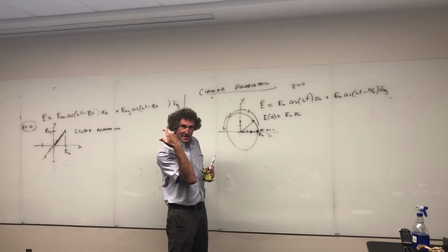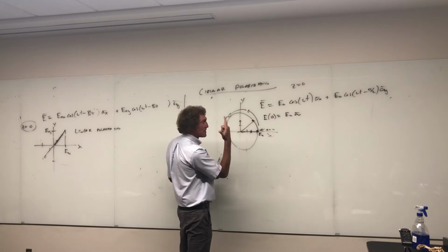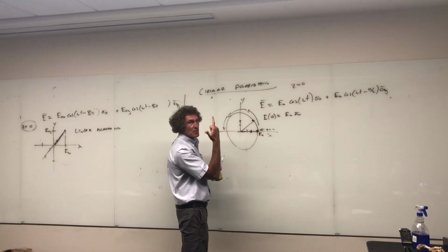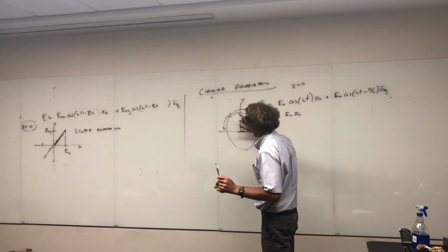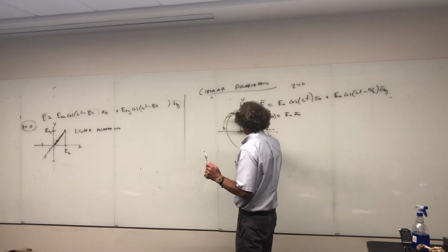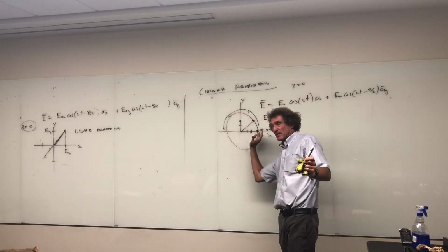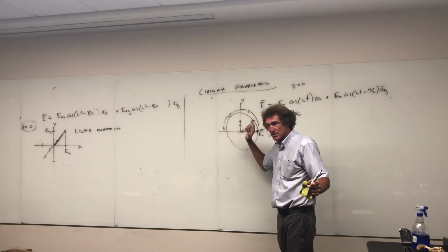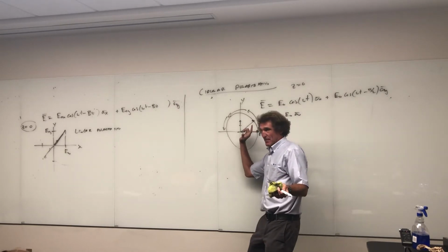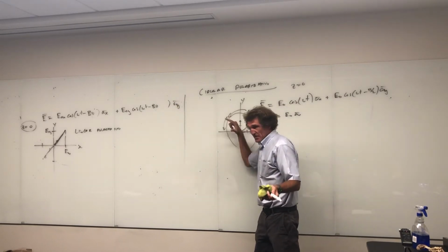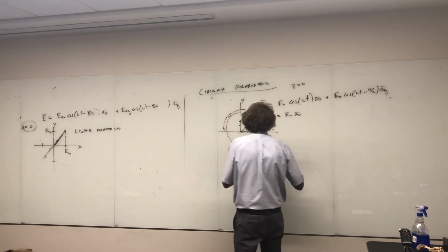If I take my right hand and put my thumb in the direction of propagation, then if I let this thing rotate like such, that's circular polarization. It's right-hand circular polarization because my right hand is literally like closing a door. If you put your thumb in the direction it's going, the fingers on my right hand, as if I was opening a door, it's going to move this way, counterclockwise. Do you follow me? That's right-hand circular polarization.